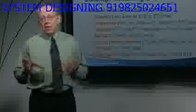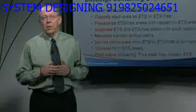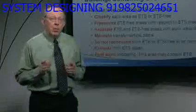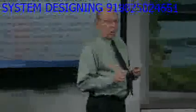Fewer and fewer buildings allow smoking indoors, so these ETS requirements are becoming less and less important to building designers. And remember, Standard 62.1 doesn't include any minimum outdoor airflow requirements for zones with environmental tobacco smoke.